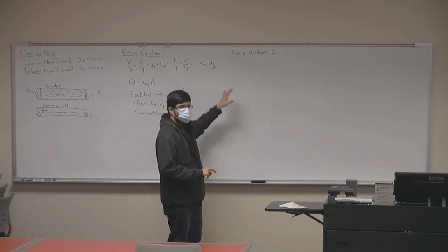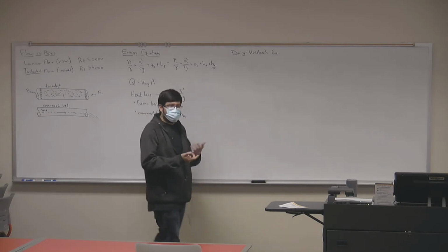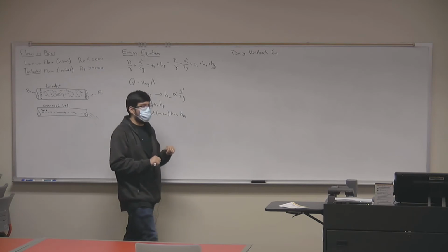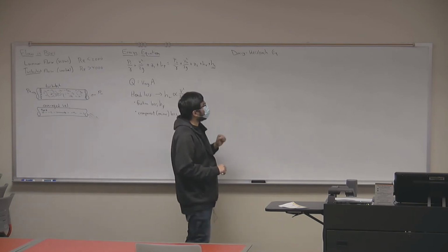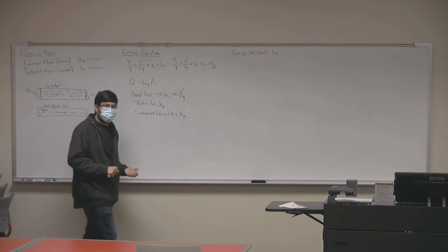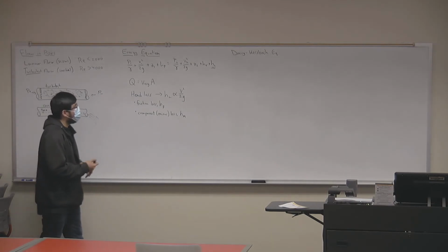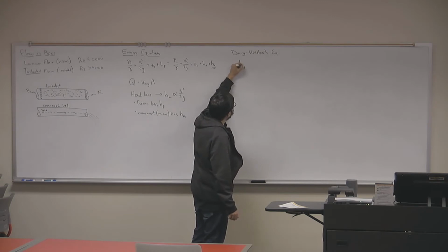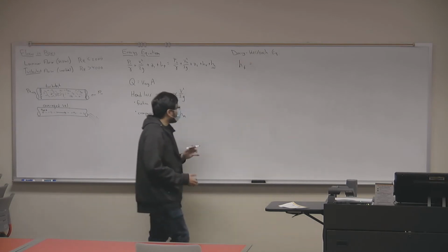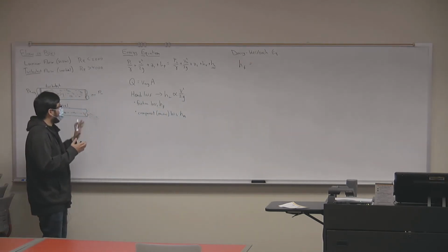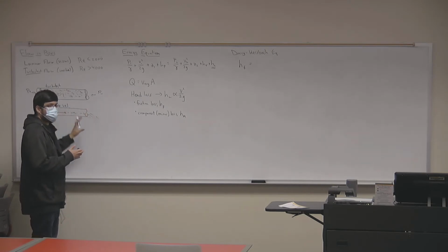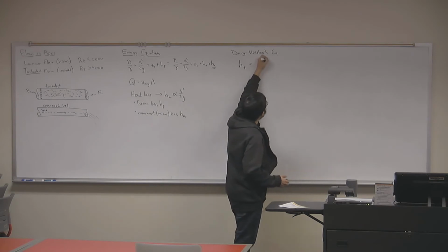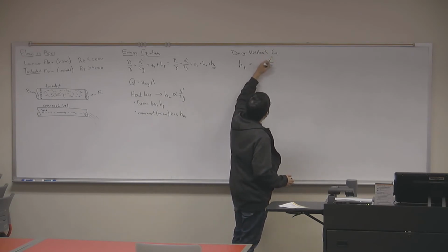So I'm going to teach you the Darcy-Weisbach equation because that is the one that most people in research and most textbooks try to push. But you'll see both equations when you are working in the field on pipe systems. The Darcy-Weisbach equation, which is the one that we're going to focus on for this class, looks at the elements of this system that cause friction and then relates them to the velocity head. We know that head loss is proportional to the velocity head.